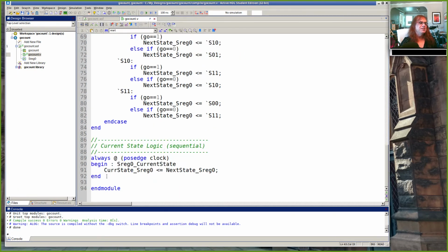And then this synthesizes a piece of circuitry so that when the clock ticks, if we want the current state to become 1, 1, it will set the inputs of the flip-flops appropriately to make that what the new output will be. So inside this is happening all of the controlling of flip-flop inputs that you did in your state machine synthesis homework.